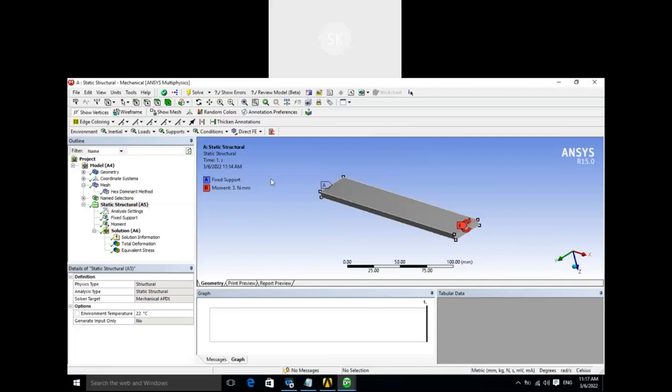It applies a linearly varying load to a surface, solid or shell. The load can be on a solid or on a surface. It simulates a fluid force acting on the structure. Fluid may be constrained or external. What is constrained? Constrained means, say, your tank, so the fluid is constrained from all four sides.